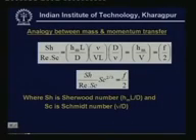So when you are applying this analogy, you can show that mass transfer coefficient Hm divided by the velocity is equal to friction factor divided by 2. This is valid for Schmidt number equal to 1. So to take care of the Schmidt number other than 1, we can modify this similar to Colburn analogy, and we have the modified analogy given by Sherwood number divided by Reynolds number into Schmidt number to the power of 2 by 3 is equal to f by 2. This is the analogy between mass and momentum transfer.